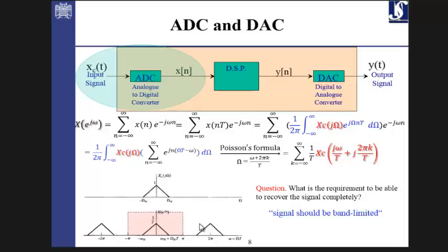You got it? Because we have omega n times T, if T is higher than a threshold, omega n T gets close to this point, and it causes aliasing with the consecutive patterns of the initial one.